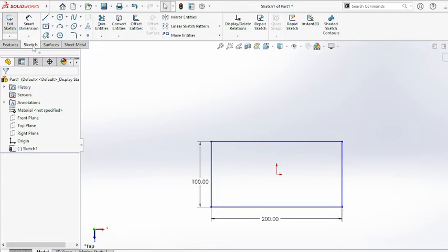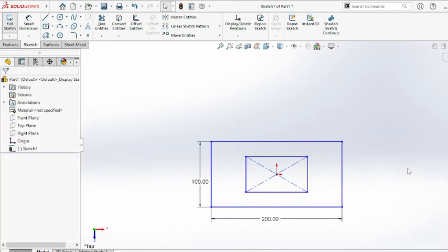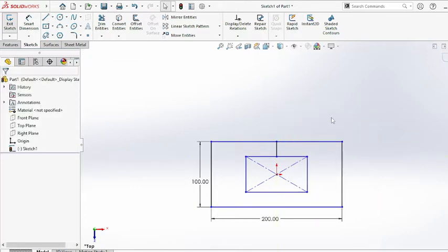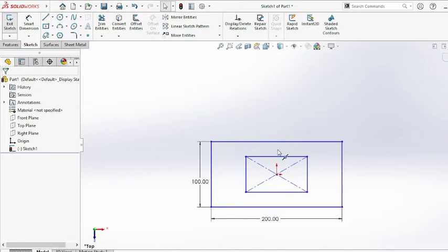Okay, for example, here I am drawing one more rectangle inside. Is this a closed sketch or not? This is a closed sketch, yes or no? Inside rectangle is there but not touching anyone. For example, here I am drawing one line. This is not a closed sketch. So no intersections are there. You can start from any point, again you can come to that point without intersections. That is a closed sketch. Always use closed sketches only, for the extrude command or revolve command, any command.